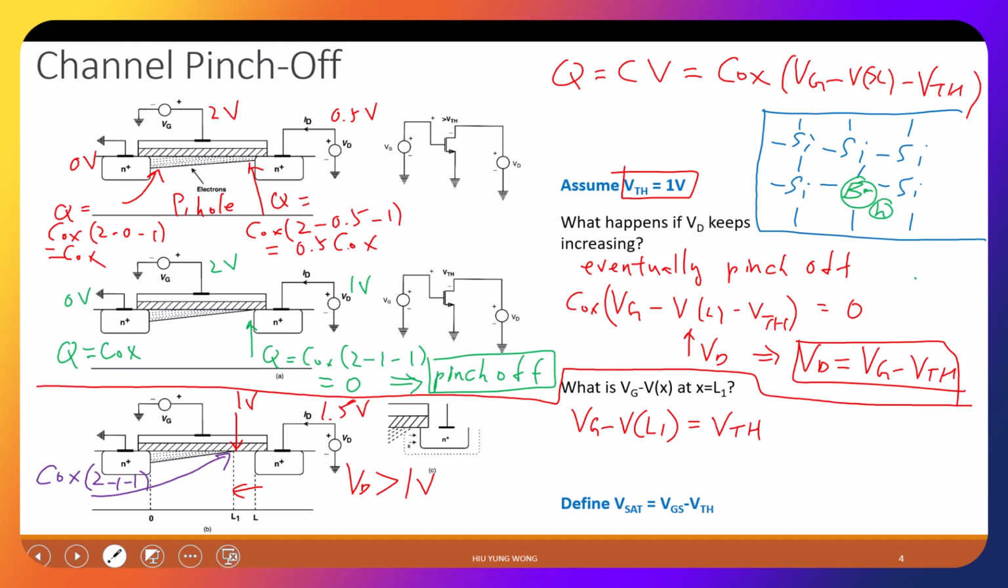Or opposite, if it's n-type, I put an arsenic, you have 5 electrons. Then I have one electron that can leave the arsenic, and then arsenic becomes positive charge. Here, boron becomes negative charge. So depletion is talking about I remove away this hole, then now I have a negative fixed charge in that region. Make sense?